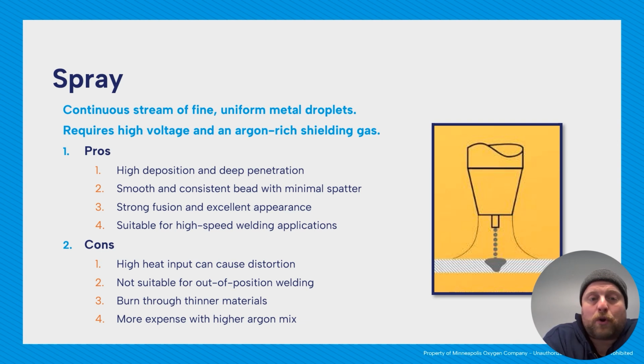Some pros of spray: high deposition, so we're putting down a ton of metal, and deeper penetration for thicker stuff because we have so much energy. You get a very smooth and consistent bead with minimal spatter. You get strong fusion and excellent appearance. I think spray welds look great when you do them well. And you can use it in high-speed welding applications. I know a lot of cobots and automation will use spray or a version of spray with pulse.